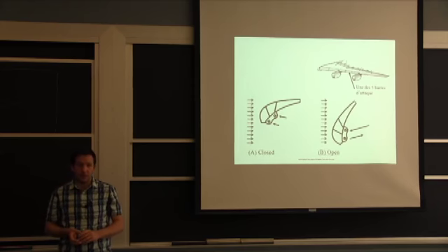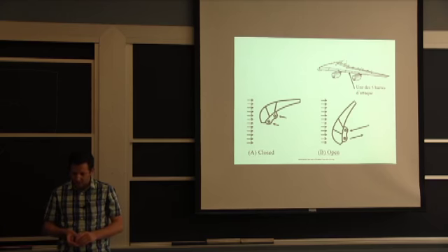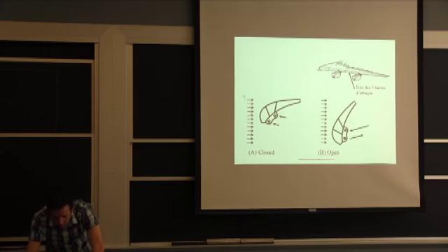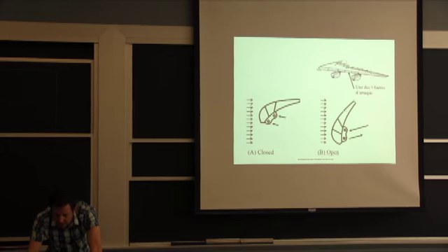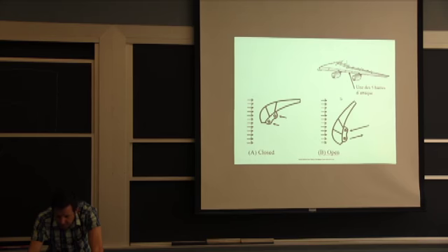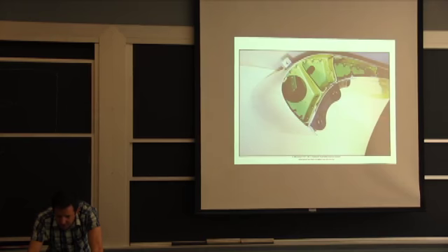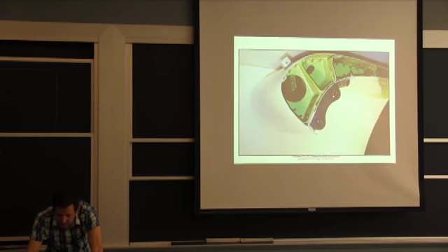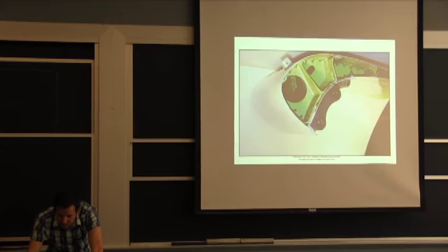And I have an example that I mentioned in the very first class, but I want to go through it in more detail now that we pretty much have more knowledge. It's essentially the component that's keeping this whole leading edge in shape. It's holding the skin, so it's an interior structure. It's also connecting to the hydraulic system for opening and closing the flaps. Here, the leading edge, essentially, for takeoff and landing. So you have it here in green, painted, and it's the same component that has the holes in it here. As you can see, it has a lot of fasteners going through it from the aluminum skin to the titanium.